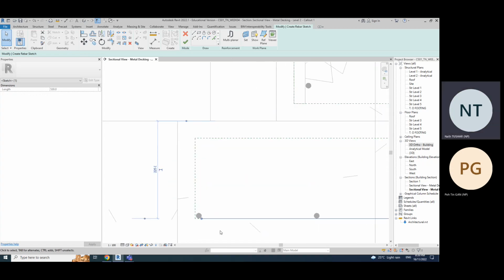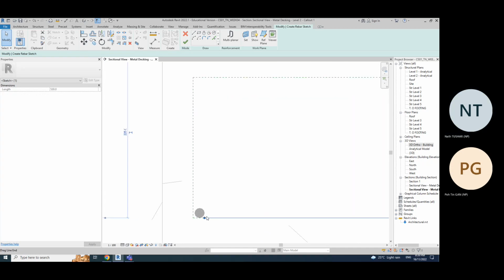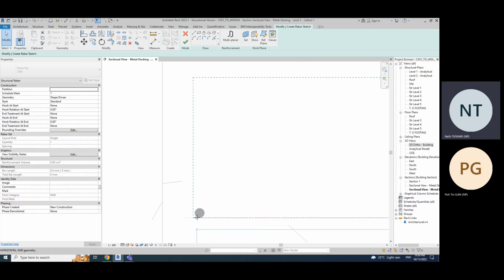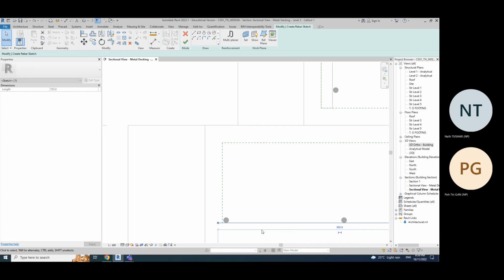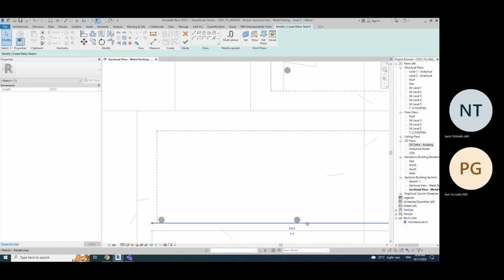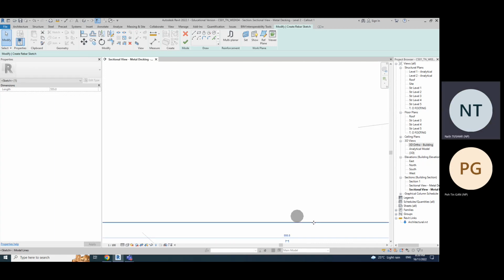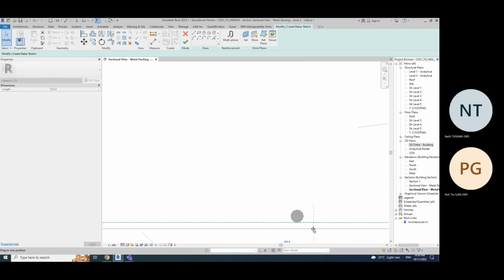Okay, so as you can see, for those who are contractors, can somebody tell me this definitely should not be the correct way, right? This rebar should have a little bit of spacing like that, right? Correct? Yes. So the bottom relatively looks okay.